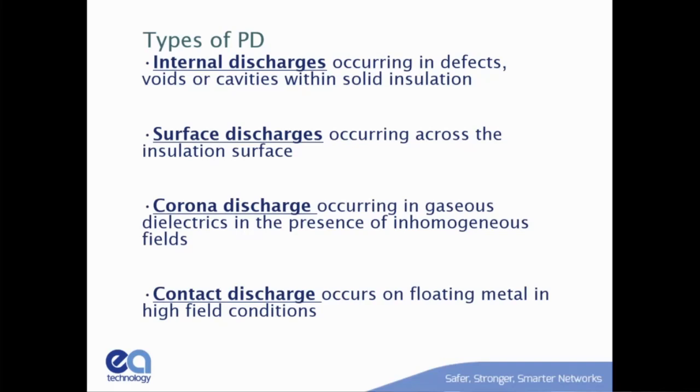My favorite one is a customer that left a bucket full of tools in the back of a cable compartment and then energized it. They had these tools in a Home Depot bucket. The metal on the tools made a perfect discharge site, and horrendous amounts of partial discharge registered on our monitor. Fortunately, they were able to de-energize it, took the bucket out, and life was good. The guy whose tools they were was nice enough to carve his initials into the handles so no one would steal them, and he had a bad day. But fortunately, they were able to find this problem and solve it.